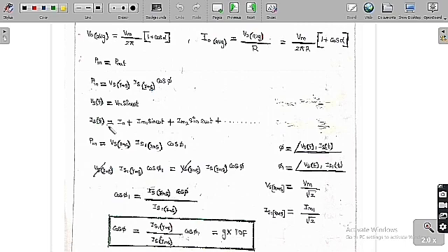So if you write it in terms of sine and cosine, let me assume we get the expression I naught plus Im1 sin omega t plus Im2 sin 2 omega t, and so on. So the input power P is equal to, taking only the fundamental values, Vs RMS into Is1 RMS into cos phi 1. We can call this the input power due to the fundamental component, where phi 1 is the angle between the input voltage and the fundamental input current.